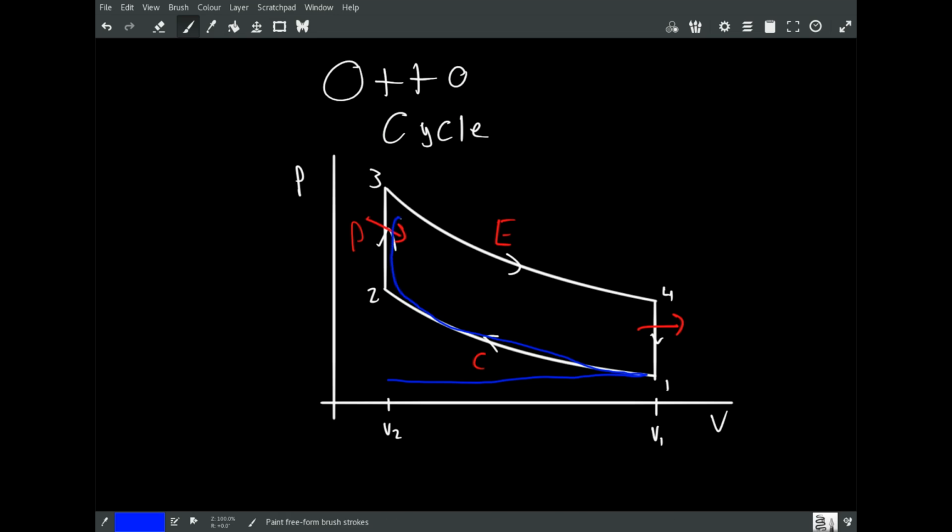You don't quite get to that point up there, and then you have, again, an almost isentropic expansion, and finally, exhaust here, slightly higher pressure there, and then it goes back around. So, essentially, the Otto cycle is going to give you results that should be similar to the actual cycle.